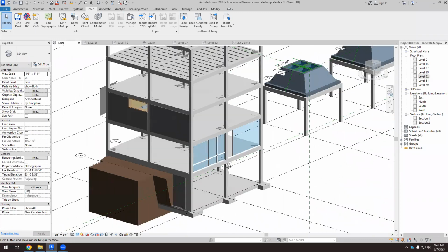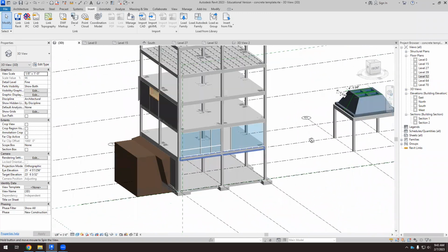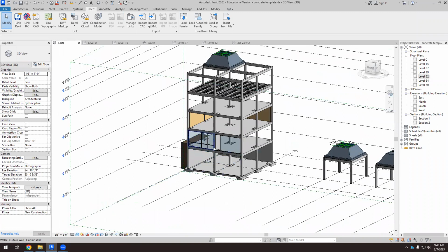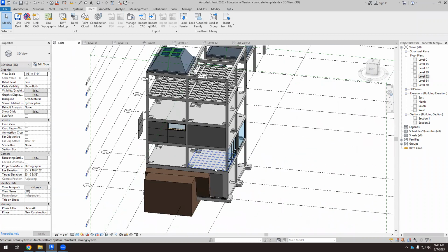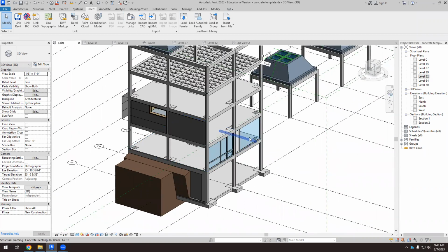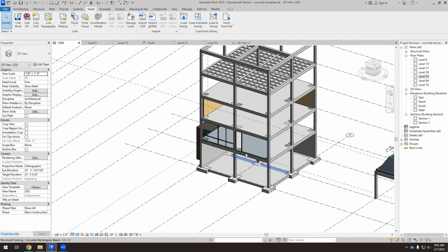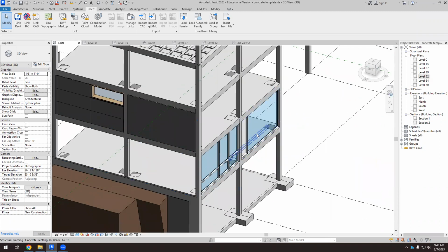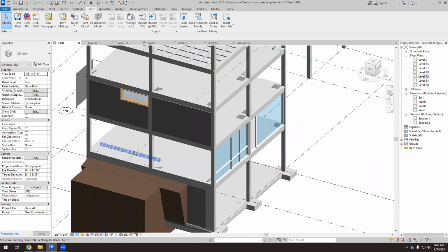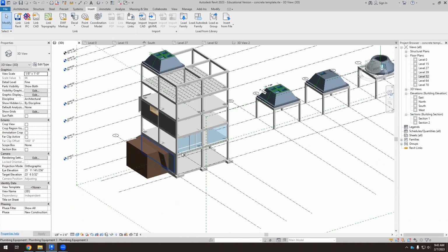Okay. So again, you have to use your imagination or your creativity to create different curtain panels in these 4 elements. So we have a corner here. You have to fill this corner with 4 different curtain panels. So try doors, mullions, try different things. Try solid and transparent elements. So don't do one and copy this 4 times. I don't want you to do that. I want you to try 4 different things for this.